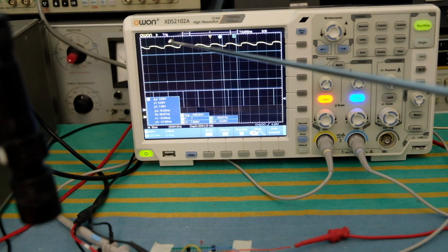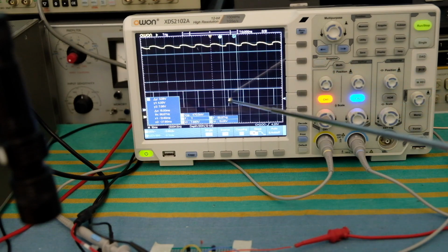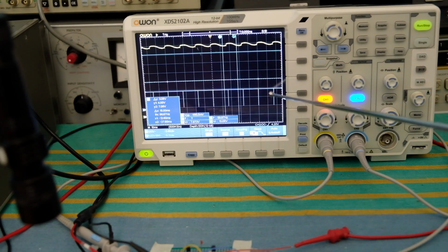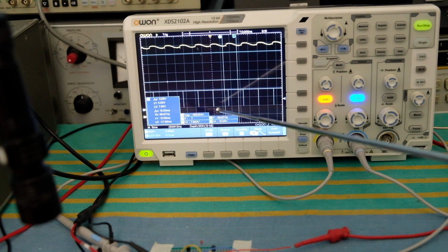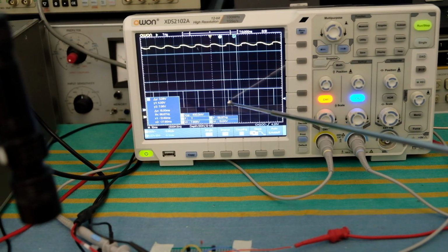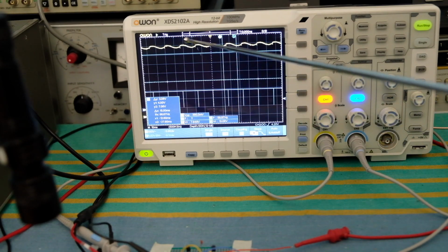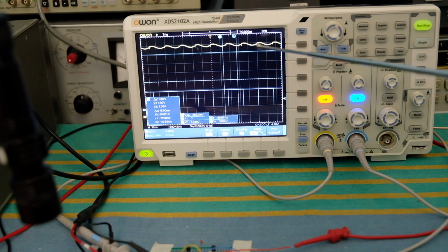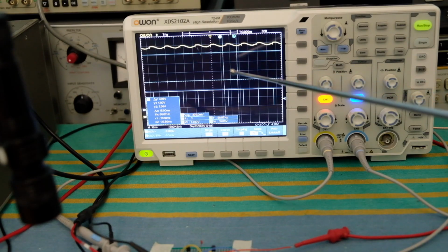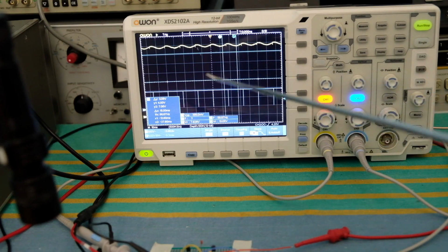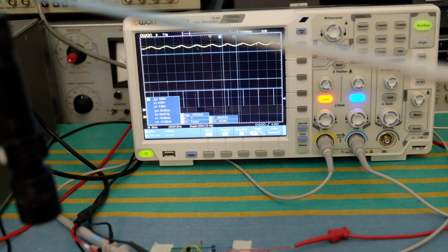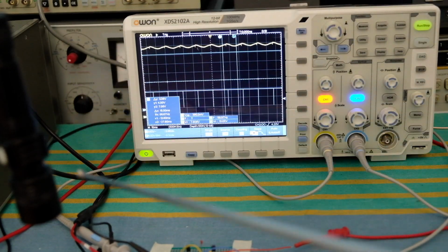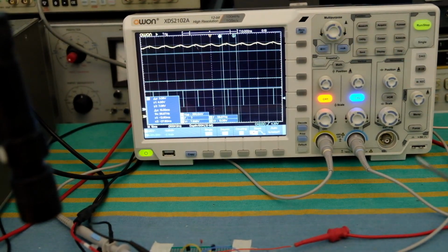There is still that modulation you can see happening, but now it's synchronized to the 60 Hertz. Roughly, this reset is occurring at the line frequency of the mains, also 60 Hertz, and this is almost synchronous with that. You can see there's some amount of movement left to right, which is because of the frequency difference between the AWG and the actual mains frequency, which is creating the lighting in this room. Now if I turn on the bright light over here on the blue LED, let's see what happens.